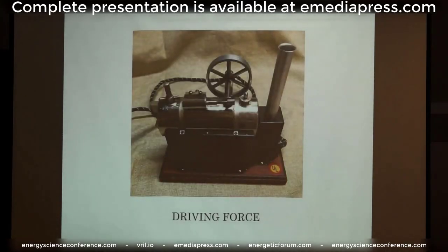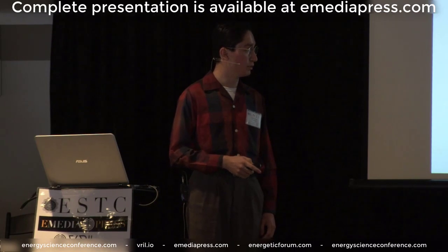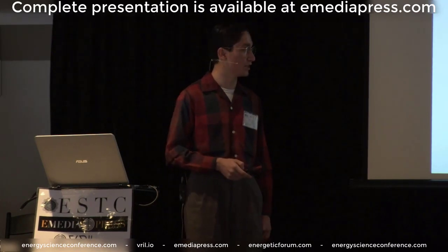So what I was using to drive it was a Jensen steam engine, which was pretty practical at the time. I used a belt connected from the flywheel to the generator, and this spun the generator, producing about 30 cycles. It's not ideal, but it was better than nothing. But then, unfortunately, the final result was that the total impedance of the coils within the control transformer was too high, and thus the power produced could not be stepped up by the transformers, or the transformer substations as I like to call them, which would step it up to the high side and then step it down to the consumer side. It would only put out a few millivolts. So that was an unsatisfactory result.